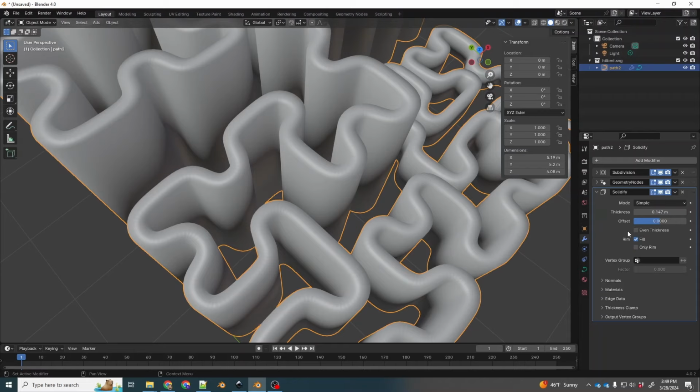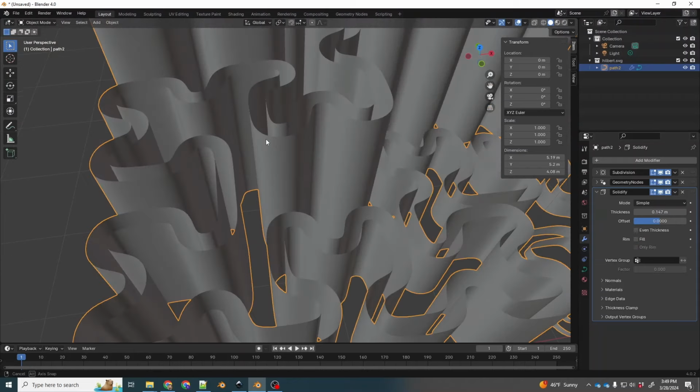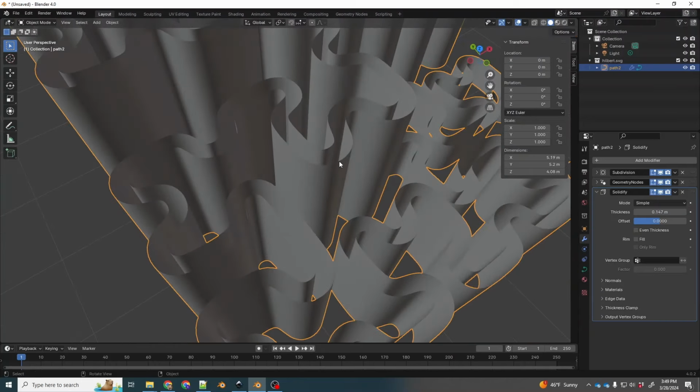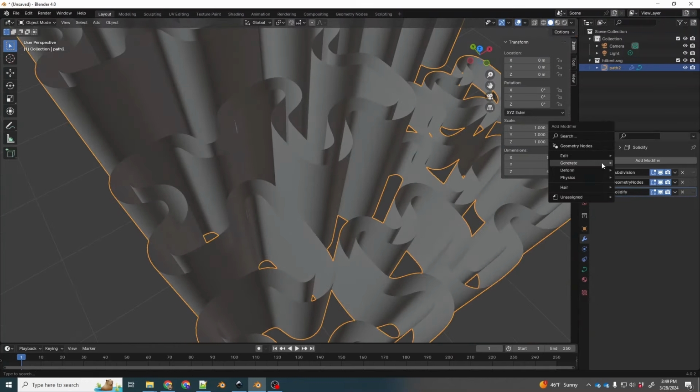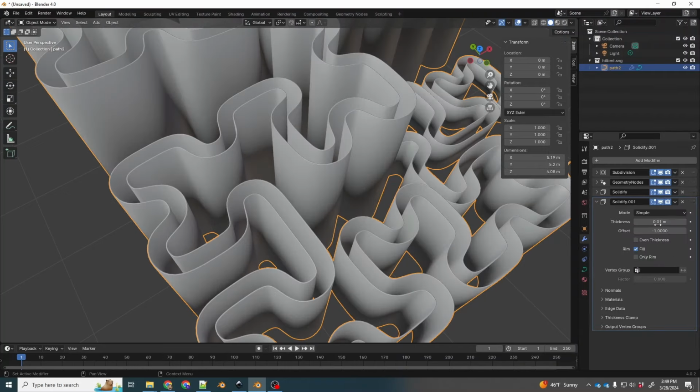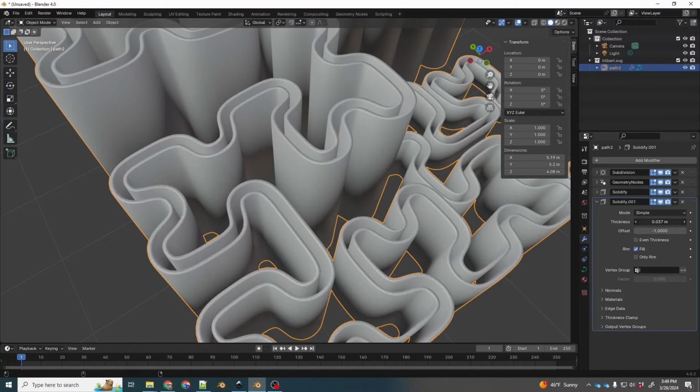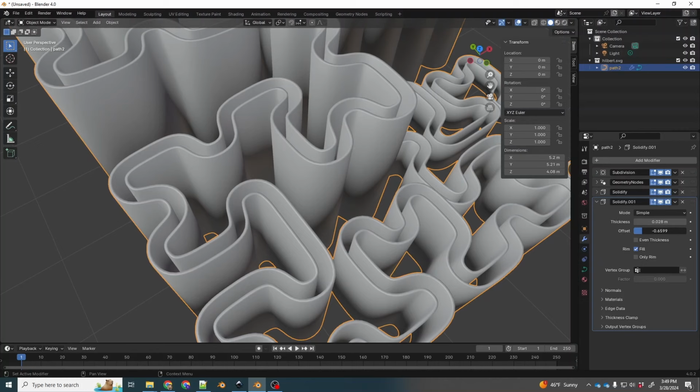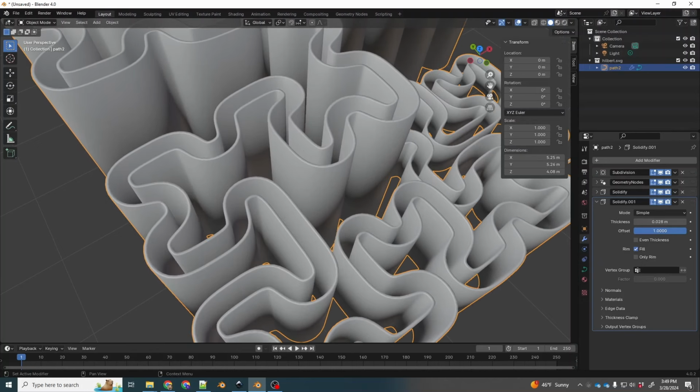What we're going to do is remove this option called fill. So it creates basically the walls with the track right in the middle. Okay. And then what you can do is apply another solidify modifier. So generate and solidify, and then increase the thickness to your liking. We don't want to encroach on the path, so I'm going to probably set the offset to the outside. Yeah, this is the outside.